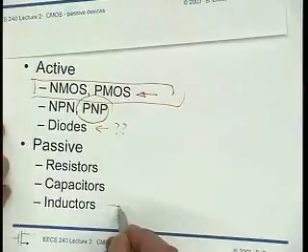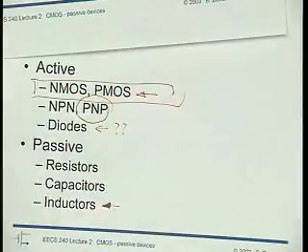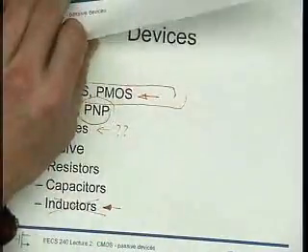And inductors, well, for mixed signal design, hundreds of megahertz bandwidth or so, inductors are not really there. When we go up to gigahertz RF amplifiers, then of course we're going to use inductors. But here, the inductors we have available, we're not going to talk about that. They're not going to be useful for us. But resistors and capacitors, they are not only useful, but we actually need them every once in a while, and so let's talk a little bit about them.